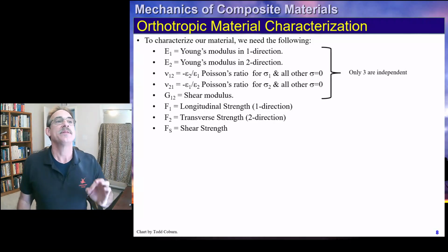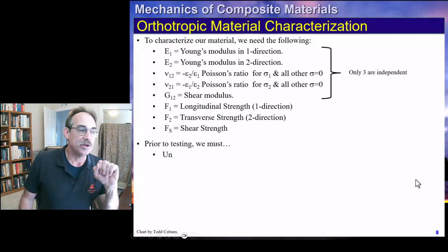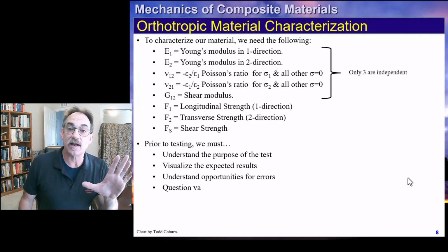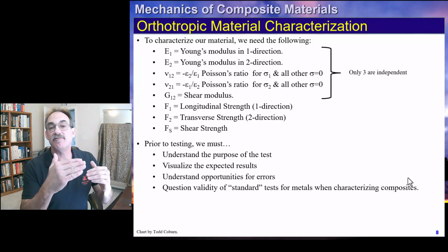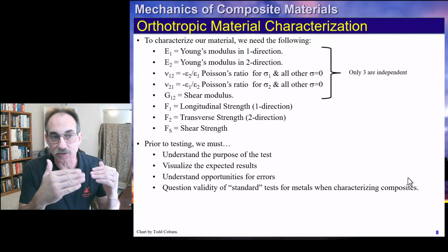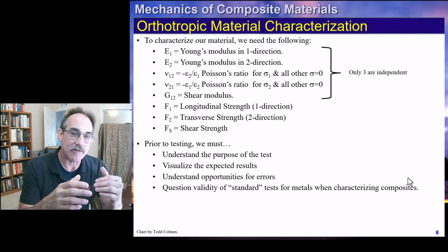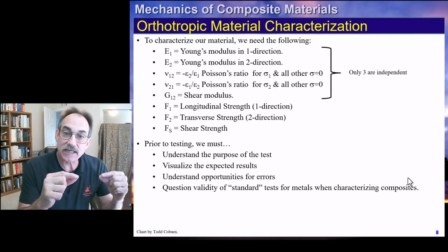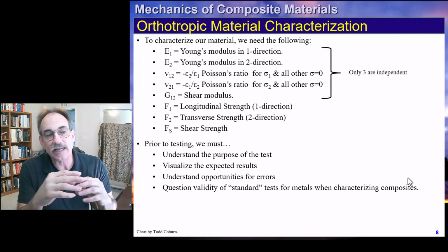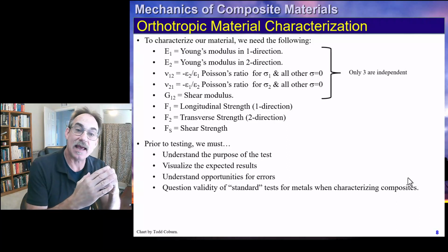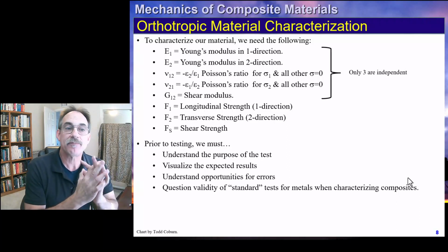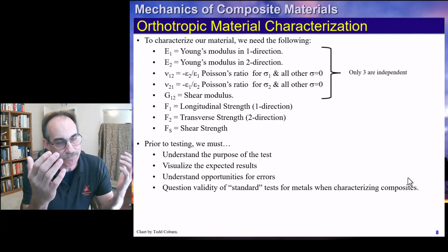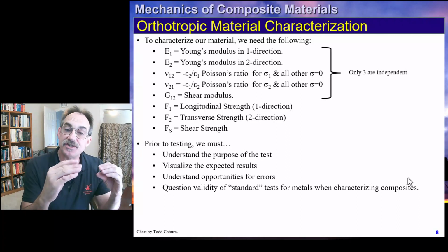So before testing, we need to understand, okay, what material are we trying to quantify? What kind of variation do we get between the materials? Do we always have, like, a 5-ply or a 4-ply graphite epoxy, or do we have doublers in places? Do we have LTM, low temperature cure material, in places? Do we have thicker doubled areas in places? Or do we have changes in thickness?